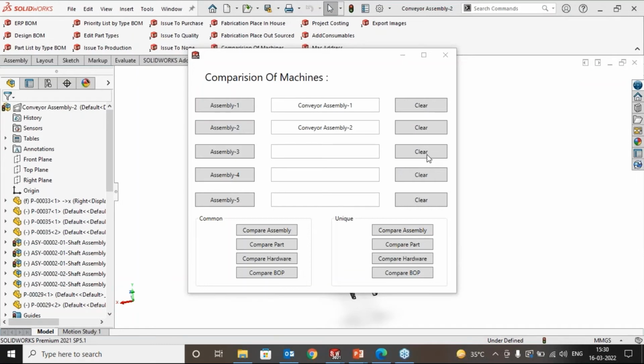Can we rename parts or assemblies in the BOM? Look, the reports which are generated out of our BOM Creator, we normally keep them write protected so that no manual intervention is done. Any renaming or anything else that you need to do, you do it before preparing the bill of material.